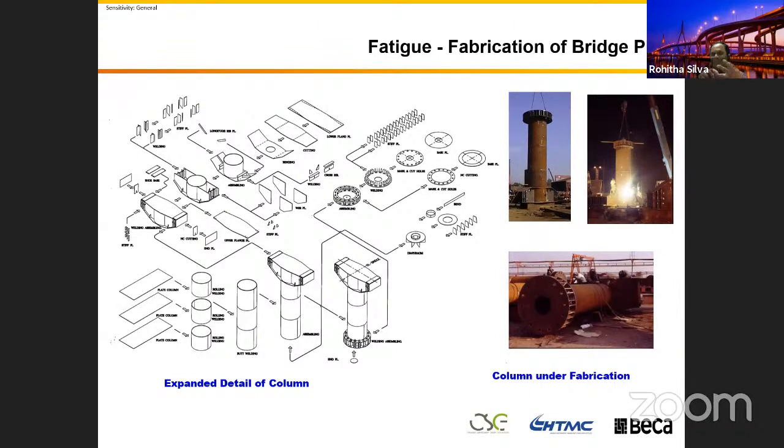It's very important. Fatigue is caused by the reversal stress in our bridge. The bridge is subjected to traffic, and because of that, the traffic load will produce the reversal stress. So the live load, for example: you know the live load bending moment, and if you divide it by your section modulus, you can calculate the stress variation. So you know what your stress variation is.